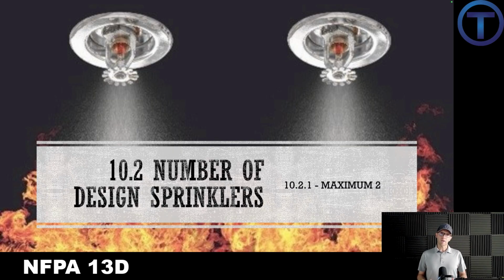10.2 is an important one, and it's very simple. It gives us the number of design sprinklers. They say at a maximum, we should have 2 in any room or compartment. Now, why only 2? Well, if you'll remember, these systems are designed basically for one head opening in one place at a time.